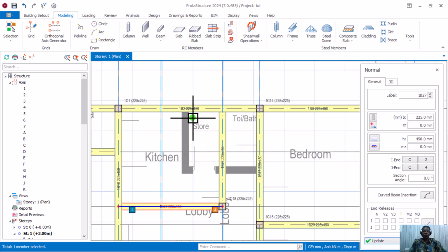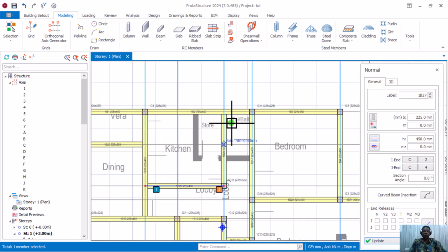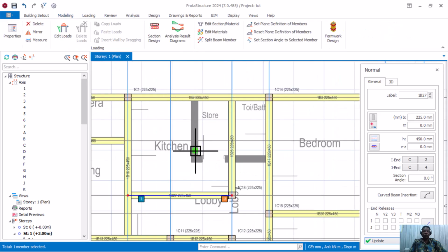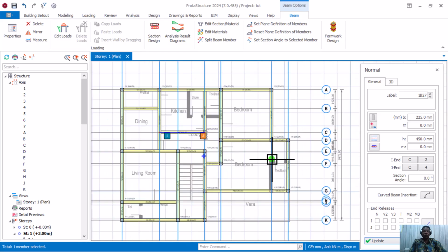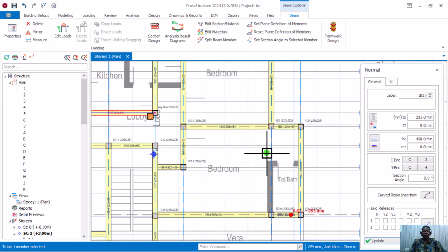So you can see now, I don't want to insert a beam here because I want to consider this to be a partition wall, right? These are separation walls between the toilet and maybe the kitchen. You just want to create separations between particular rooms, the kitchen, the toilet, or maybe domestic areas. So that's what we use partition walls to do. So in this regard too, I'll be considering this as a partition wall because I don't want to put a column here, because if I check, the whole of this panel can carry my slab for me to be able to